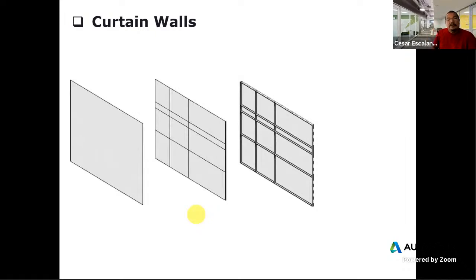And you can have different mullion profiles for different purposes. For example, you can have the top mullion have a structural purpose, or the vertical ones have a different function from the interior ones, because one is going to have attachment mechanisms to the adjacent structure.